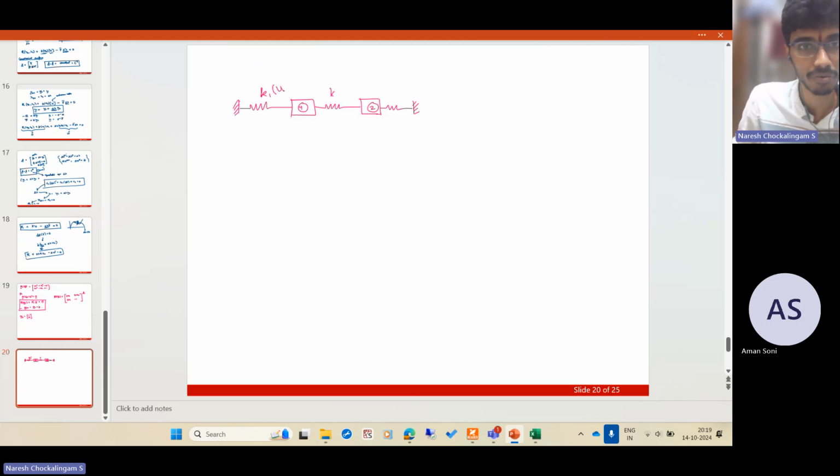So this is K1 of U. Or let me do it this way: let's say this has a force response F1 of delta, where delta is the extension. This has a force response F2 of delta, and this has a force response F3 of delta. So these are the internal forces. Now you can use any method to arrive at the equilibrium equation. You can start with the internal virtual work and external virtual work also. That's the easiest actually, if you see.